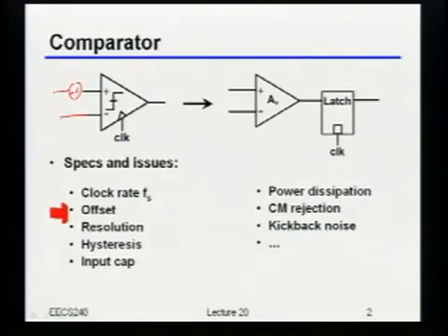Okay? As we had talked about already in the context of the high-speed links. So I'm going to care about how I make that offset small, because like we talked about with links, if I have too big of a residual offset, then that's really going to eat into my bit error rate performance, right?